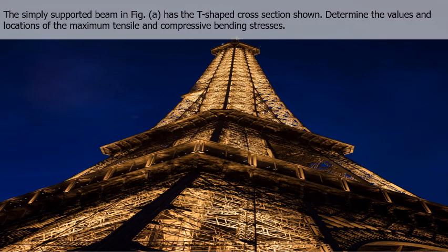The simply supported beam in figure A has the T-shaped cross-section shown. Determine the values and locations of the maximum tensile and compressive bending stresses.